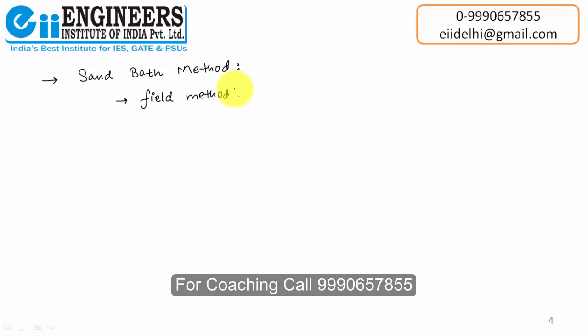So this method is the same as the oven drying method, except that we are using kerosene. Of course the water content is determined by the same equation as given in the oven drying method. But one thing we should keep in mind is that the heat that we are giving to our soil sample should be uniform. Okay, well, now the next method is the calcium carbide method.